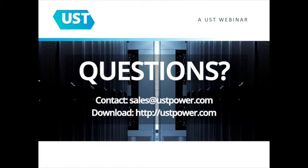And this one's from Bob. Will adding an EVR to the UPS configuration change the mean time to failure? If we add the EVR in parallel with the UPS, the bulk of the power will flow through the EVR, and the EVR's mean time to failure is considerably greater than the UPS. So the aggregate effect of adding the EVR would be to increase the mean time between failure of the whole system, which is a big plus.